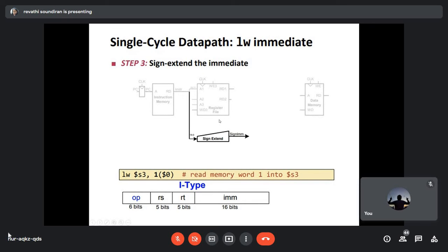Now this is going to hold the immediate value. Since we are working with an immediate value, you will have an operation for carrying out the sign extend, which gives you the signed immediate value. This is 16 bits, bits 0 to 15 from the instruction decoding, which is the immediate value. Upon decoding bits 0 to 15, the first 16 bits are occupied with the immediate value. In this case it is 1, and the corresponding value is passed from the sign extend.